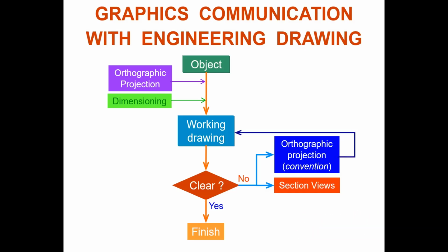Sometimes there is something wrong with the orthographic drawing, and people still cannot understand what the part is that you are trying to describe. So you have to modify your orthographic to make a section view, because we have to be right the first time. If you follow this topic, you will understand sectioning: one of the views of your orthographic will be replaced by a section view.